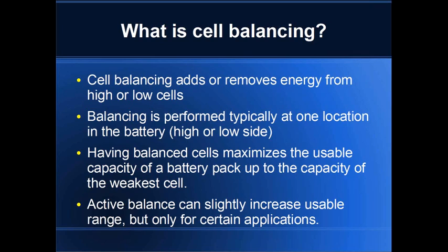Lithium battery packs, as long as you've got decent quality cells, tend to stay in balance quite well with each other. And if you're using an intelligent balancing algorithm to go in and just make minor tweaks to the state of charge every time you charge, or every few cycles on the battery, even if it's once every week or month or something like that, you don't typically need to waste a lot of energy. It's usually more cost effective to burn that off because you can just use a small resistor.